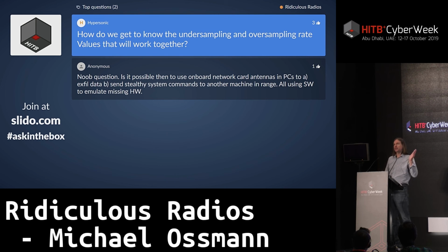But if our sample rate was like 1,000th of the frequency of our target, it probably would not have worked, because the higher in frequency the target signal is relative to your ADC frequency, the limiting factor is jitter in your sample clock. It actually affects things worse the higher up in frequency your target is. Again, there's no hard limit. It just depends on the quality of your clock.